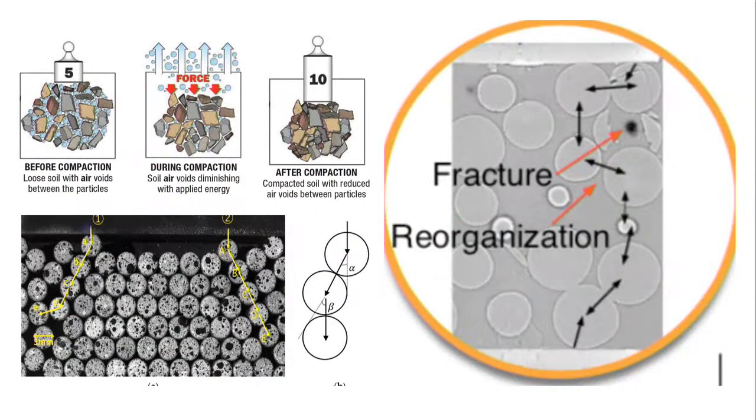So how do you compact systems? Well, there are two ways of compacting. If you shake them mildly, then you open up little gaps, and within the gaps the particles tend to fall off. But if you are doing something like this, which is a dynamic compaction, you're going to bang against it, and then there are going to be some force chains upon which the load is being transmitted from one point to the other. In all likelihood, when the force is large, this particular chain is going to buckle, bend, do something. There is going to be some kind of a mechanical instability associated with this force loading chain, and that will be what leads to compaction.